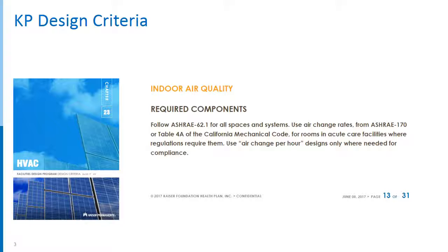Because I should mention, there's no actual known benefit to the air changes. The occupants of the buildings don't know the difference. There's no clinical implications. Obviously, there are folks at ASHRAE or FGI who say, well, you should use air changes, but even they can't articulate why or any benefit that's associated with it.